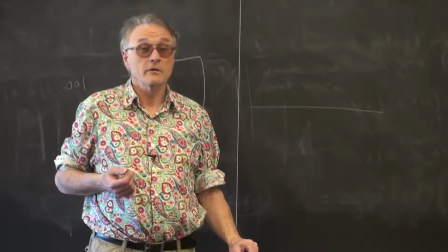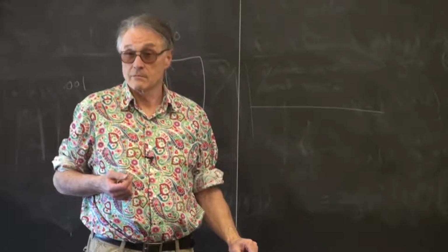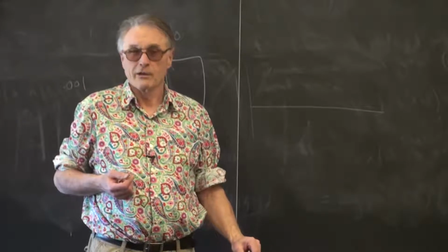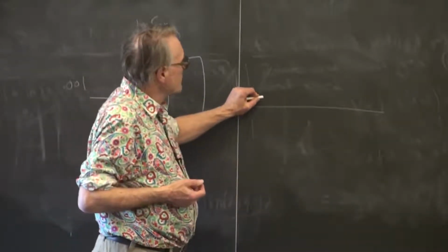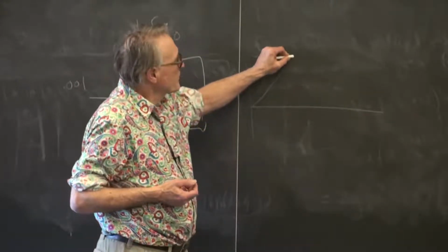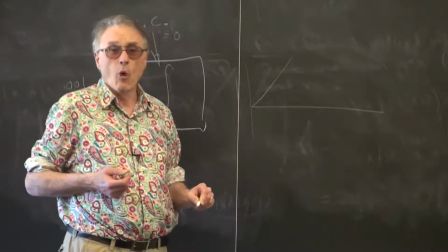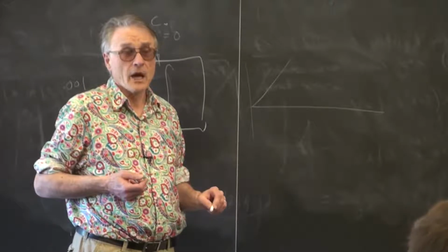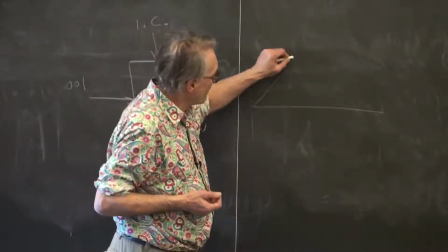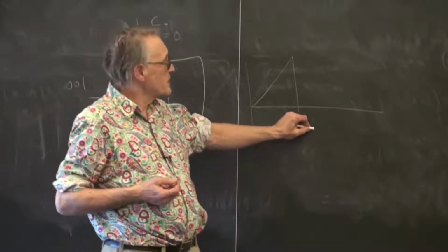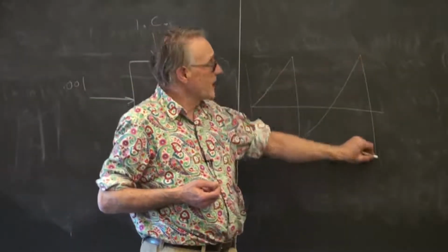What happens when you integrate a constant? You get time out, right? So you'd expect this to increase, get to some maximum, 1.99, and then wrap to minus 1.99. Boink. So what you're going to see is something that looks like this.